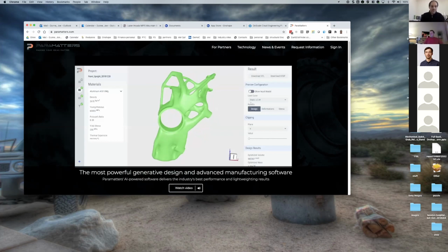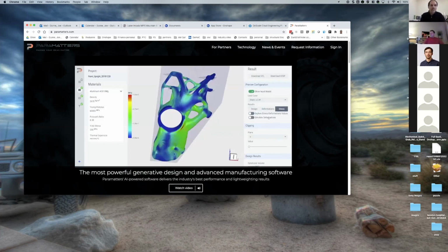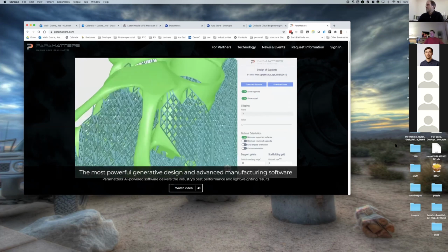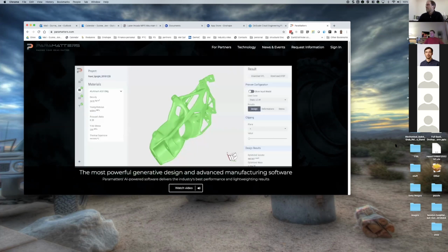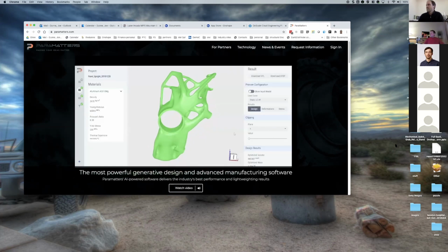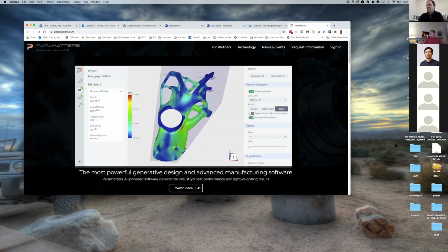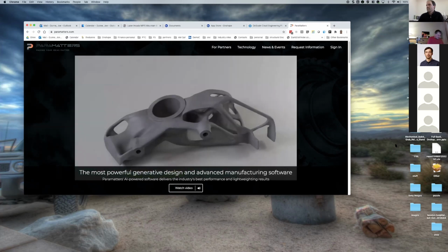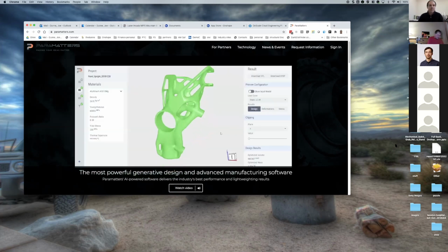Where I think this stuff becomes really practical or more widely used is, let's say you're doing CNC and you only have a 3-axis machine. Instead of having a part with undercuts that you couldn't cut with a milling machine, you'll be able to give it a manufacturing process, and it will give you a shape that's still optimized this way, but won't have undercuts. It will look more and more manufacturable. You can go all the way from 2.5-axis to a 5-axis manufacturing process.